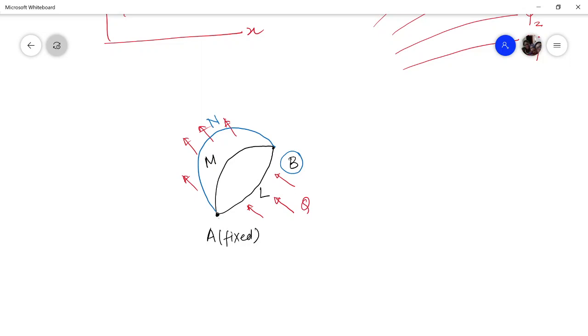That means if I extend this line further from point B in this direction, then what will happen? More amount of discharge can be accommodated, and more can be leaving. Therefore, this point B position, or the placement, is what the rate of flow or discharge is a function of. And this positional function is what we call a stream function, represented by psi, which you have already seen.